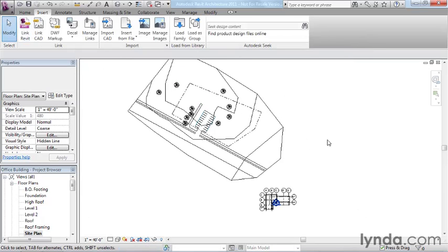Now here's the file. You can see it's a simple site plan file with a couple roads and a parking lot and a little property line. What we're going to do next is move the file into position relative to the building. Now we don't want to move the building relative to the file because we might leave some geometry behind, or we might disrupt some relationships between some of our geometry, your walls and your roofs and your grids. They're all kind of attached to one another, and we don't want to work at that funny angle anyhow.